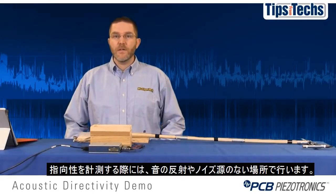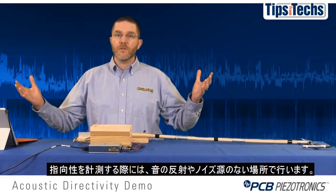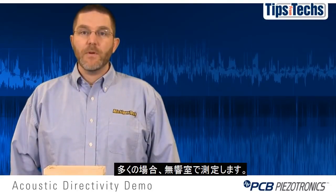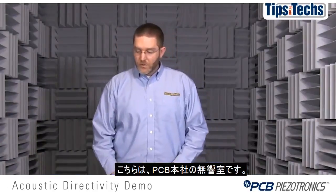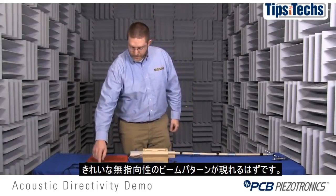When we measure directivity, we like to do it in a venue that doesn't have any reflections or contaminating noise sources. That's why we typically use an anechoic chamber, like this one in the anechoic chamber at PCB headquarters. We'll start out running the 2-channel loudspeaker at 300 Hertz, and we should see a nice omnidirectional beam pattern.